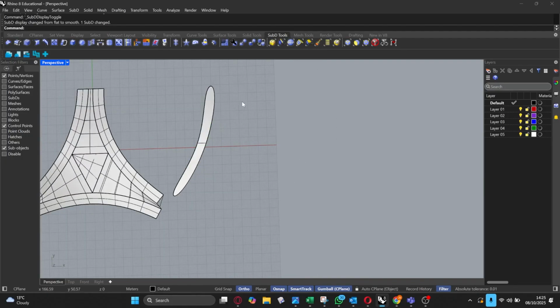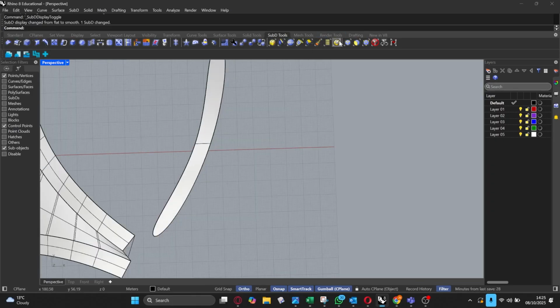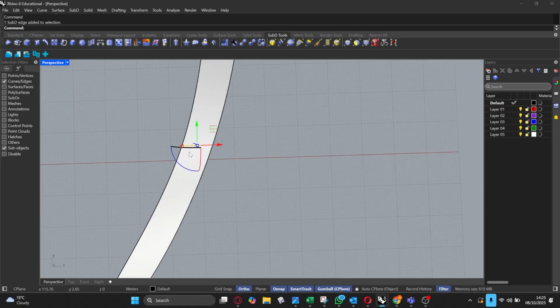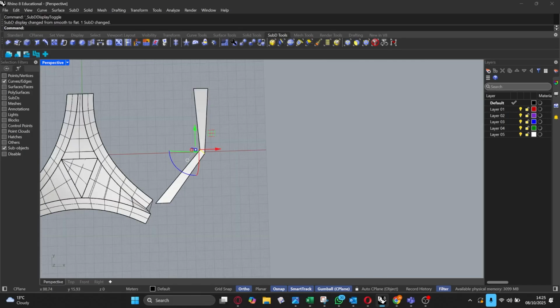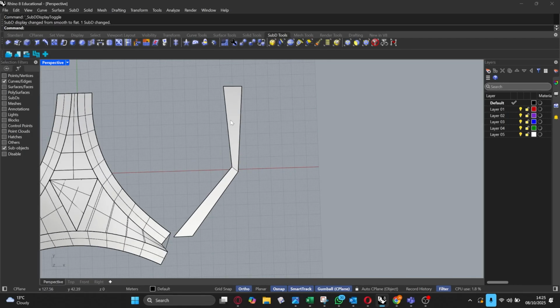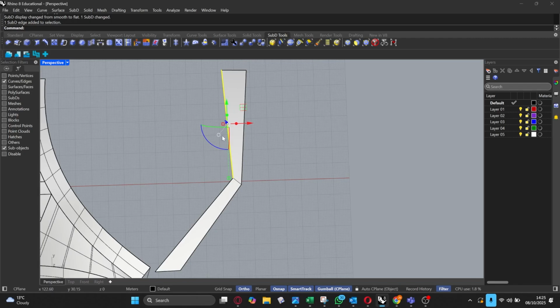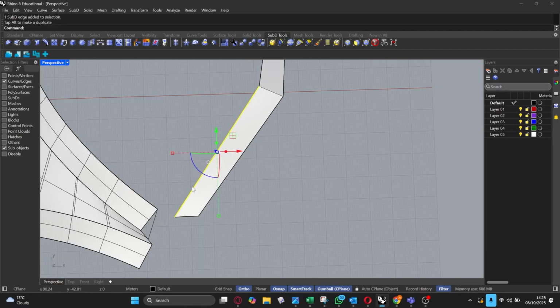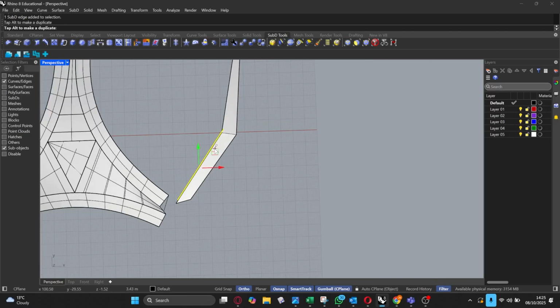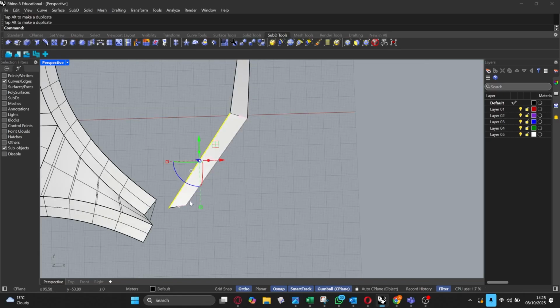Okay, so what I'm going to just demonstrate now very quickly for you is, let's say I'm creating this same face that I have here. I'm just going to go into non-subdivided mode. And what I'm going to do is I want this vertex to have more of this kind of shape. So it's so much easier to model in non-subdivided mode because you can get a real good feel for your geometry and how clean the geometry is.